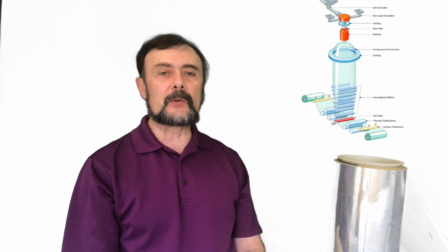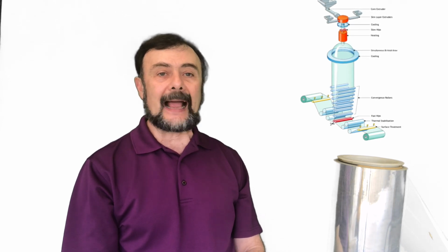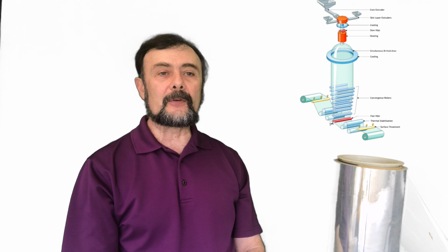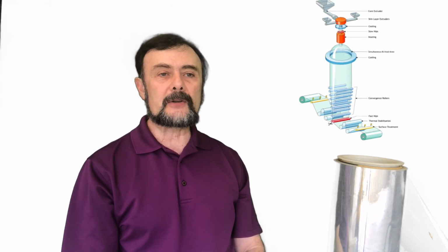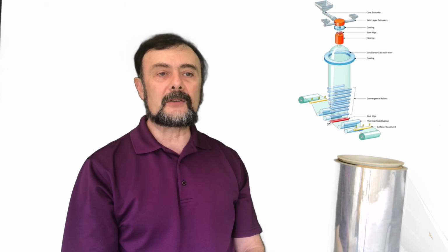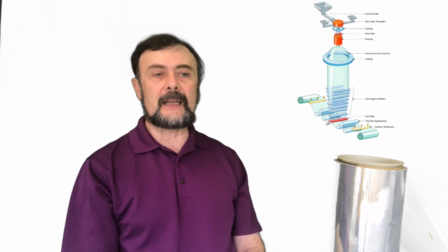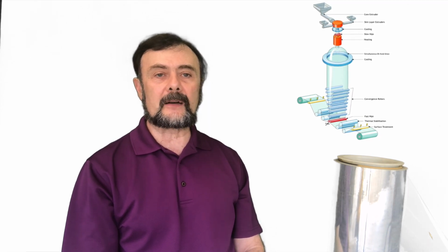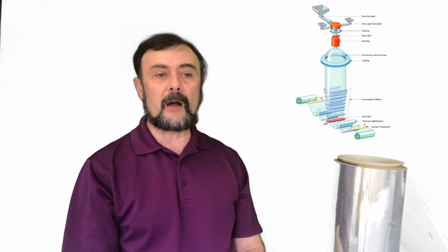Even though the plastic was all mixed up in the extrusion process, when the plastic came out, the last little bit of the die, it went from high pressure to room pressure very quickly. This differential pressure caused the shortest molecules to slip past the longer ones and concentrate near the surface of the plastic. These short molecules of adhesive would stick to the exit edge of the metal die, forming little brown stalactites. As time went on, the stalactites would grow and break off.